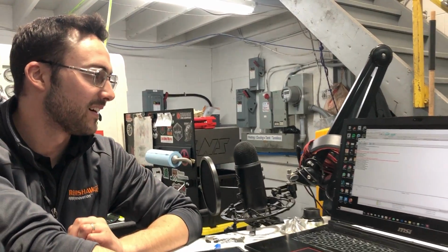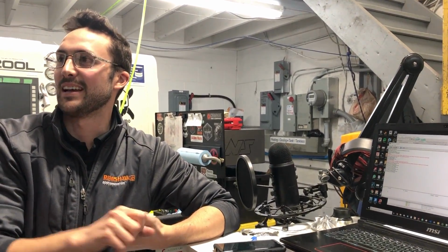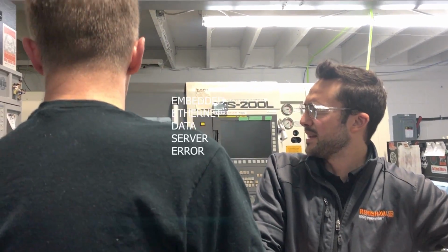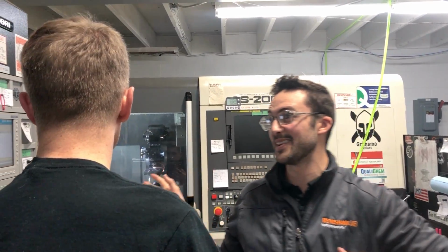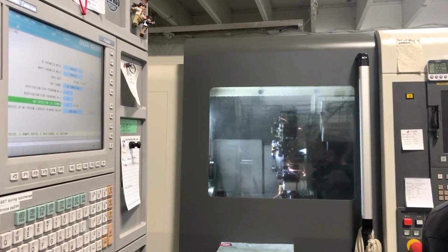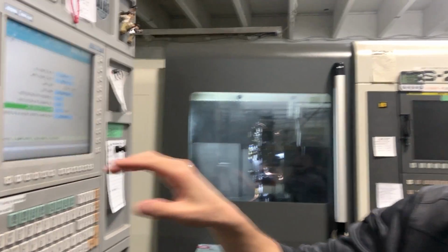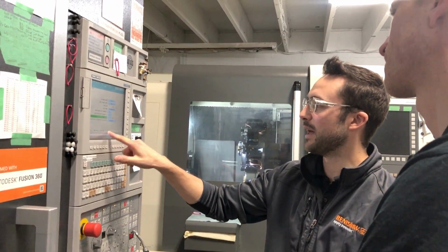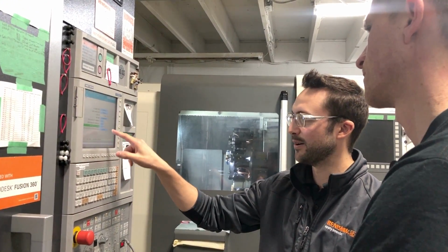I was not going to get excited there, because what we should see here is that it tries to log in, it successfully does it, and then it takes the information. So, embedded Ethernet data server error. That's a very generic error because it's saying 2 things right there, and we don't know which one it is. Well, this is one of those cases of read what it tells you. So 5 is data server, 9 is embedded, 15 is user area.